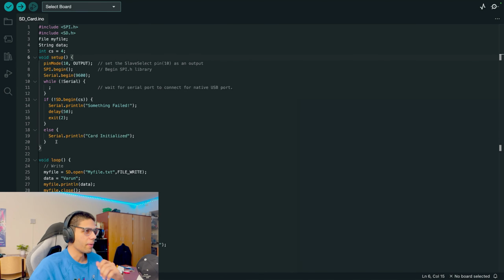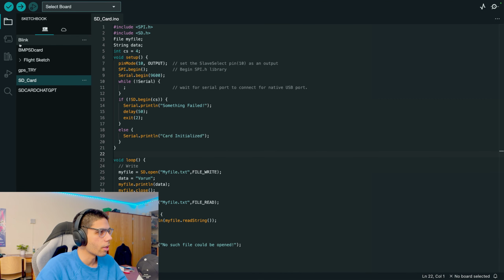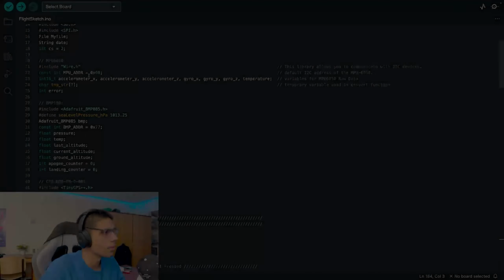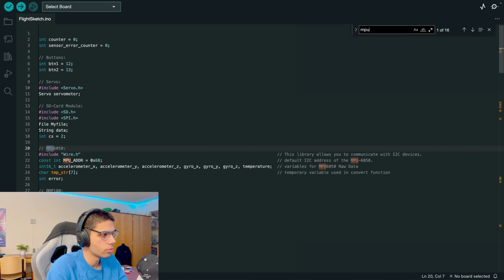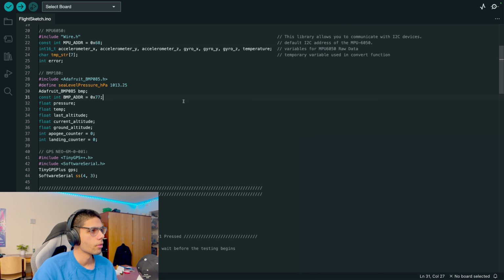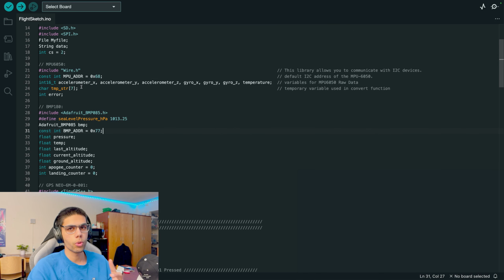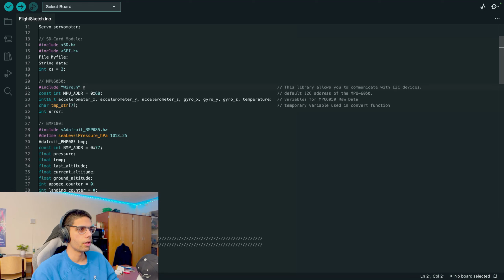And one more thing, just to add to that. Let me show you the actual code of that sensor. There should be the MPU. All right, here it is. When you go to Arduino and connect our PCB to your laptop, just like you connect an Arduino to your laptop, you can do it like this. Include this library, Wire.h, and initiate this variable.